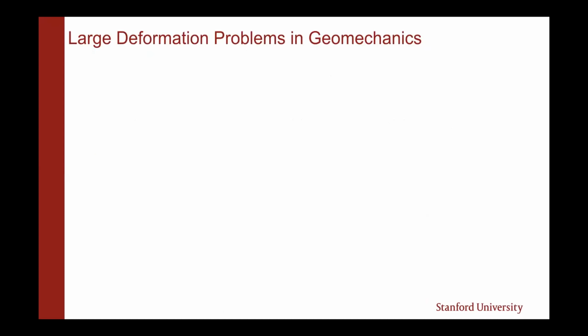If you're interested in looking at large deformation problems in geomechanics and you want to study them, one of the best ways to do it is through simulation or experiments, modeling essentially. In numerical modeling, you're using a continuum-based approach. You need to know some constitutive model. And if you're above the brittle ductile transition zone in the Earth's crust, it's generally safe to model tectonic crust as an elastoplastic material, which is what we do, or a viscoelastoplastic material.